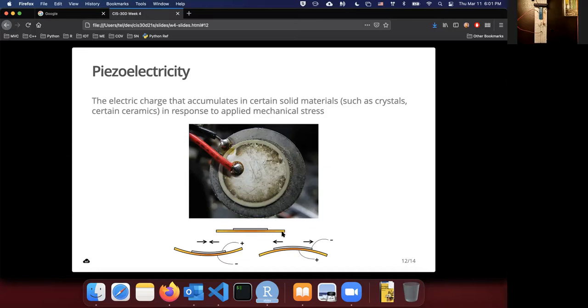You can think of this orange bar as the piezoelectric ceramic, and the little metal plate in the middle is basically called a diaphragm. When this diaphragm gets squeezed, it will bend, because there's no other place to go. When it bends back and forth, this is what makes the sound.